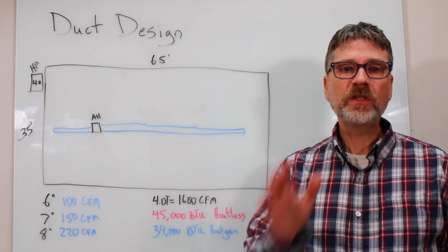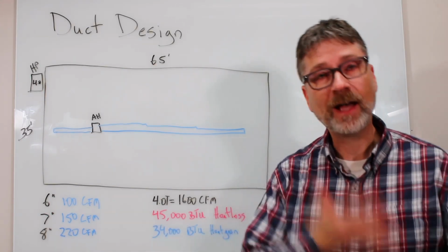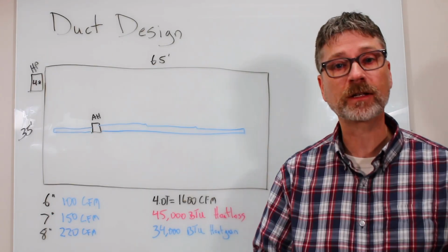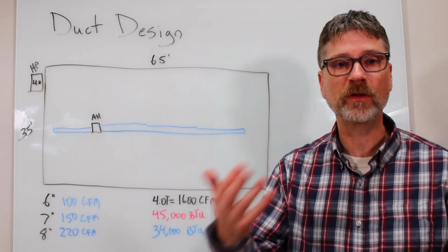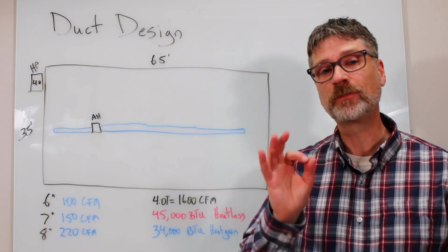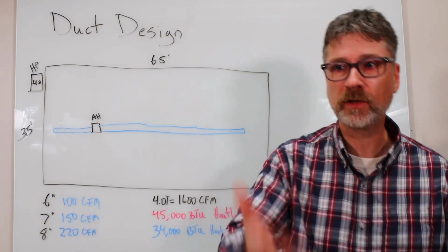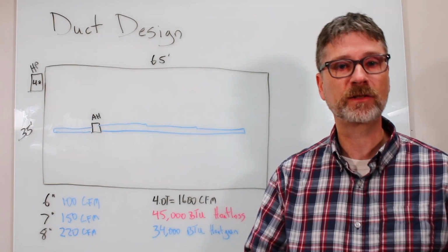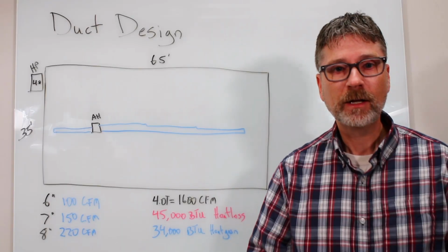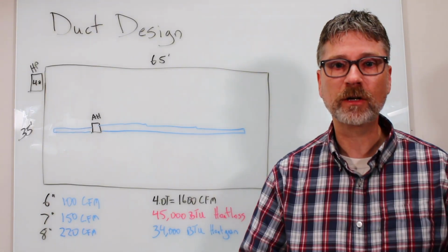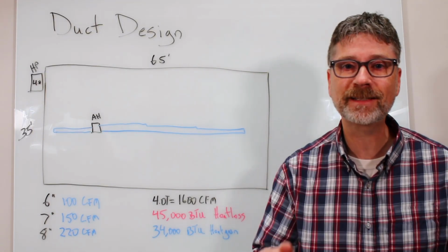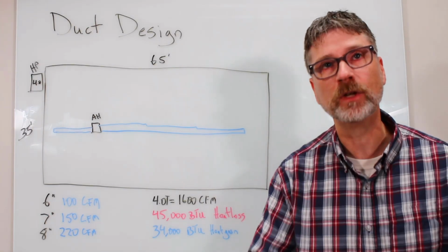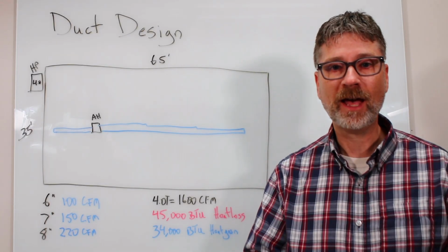Now, once you know the velocity of a duct, or how fast the air is moving through it, you only need to know the size of the duct, and then you can have the CFM, or the volume of air that it's moving. And it's really CFM that equipment, furnaces, air conditioners, heat pumps, whatever, those equipment units are sized to. So, let's do an example. Say I'm at a register, an outlet register, and that register is fed by a 6-inch metal pipe. I use my anemometer, and it gives an average reading of 600 FPM.